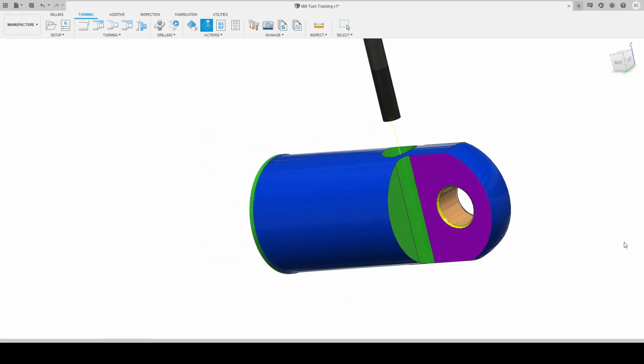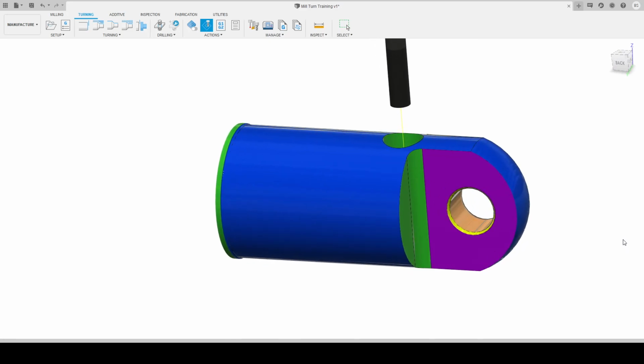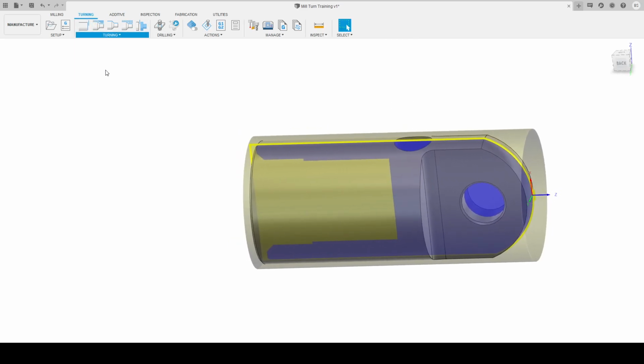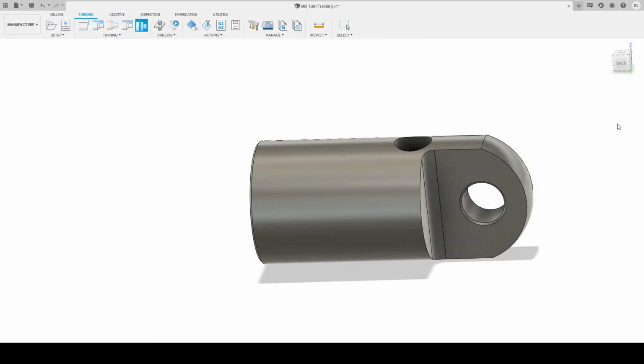Very good. Now, to part off the part, we go close and we want to go turning part. Okay, select the tool we want to use, select our document, click the plus, and for a part off we'll just go general grooving tool. Go to our insert shape, it will be square. See up there, so now we have a square insert. The width of the insert, so the width of the tool, is 2.7, that's fine.